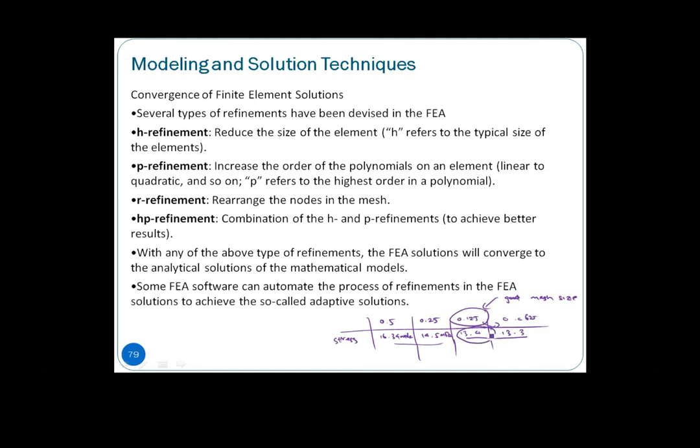So that means if you go to a smaller mesh size, it probably won't help in terms of accuracy; it won't change much. So then we have to use this size instead of maybe 0.5. Maybe it's too large and the changes are too much. There are still a lot of changes when you play around with the size, so it's still very dependent on the sizing, right? So that is what we call the mesh independence test.